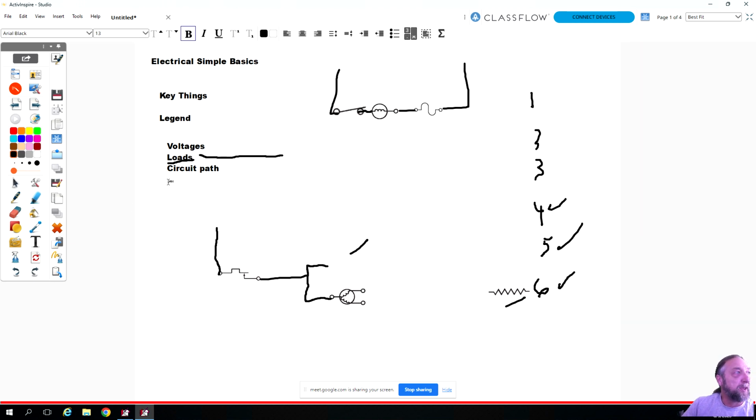The controls that control them, they could either be controlling them like a timer, or a thermostat is a control, but a fuse is also a control, but it's there for safety reasons. And if any safety part fails, just changing that part alone doesn't mean you fix the problem.